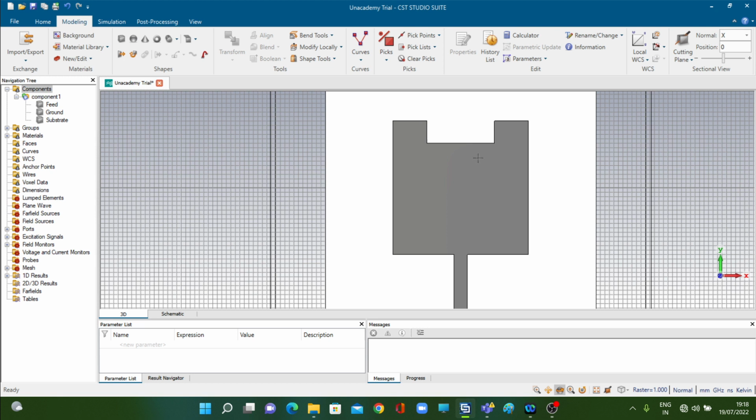Because the laws of fractal geometry state that whatever shape you are initiating is known as an initiator, the fractal initiator. For example, in our design, this rectangular slot is a fractal initiator, the first level of design modification. And each such level of design modification is called an iteration. Iteration means repetitive similar phases, repetitive similar stages. That is known as iteration.